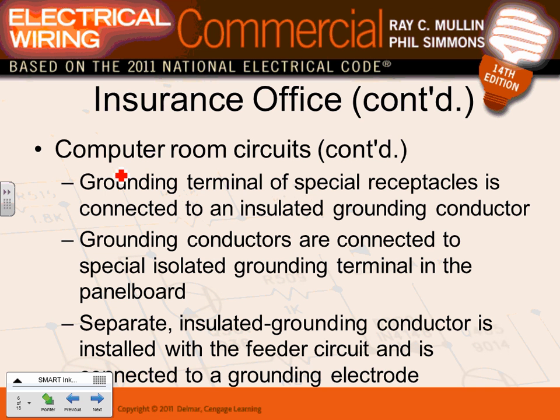Number 4, they also have an insulated ground because of interference. They don't want to interfere with these servers, so they put in an insulated ground. An insulated grounding conductor. Receptacles are insulated ground receptacles, with an insulated grounding conductor. And the insulated ground goes all the way to the surface.